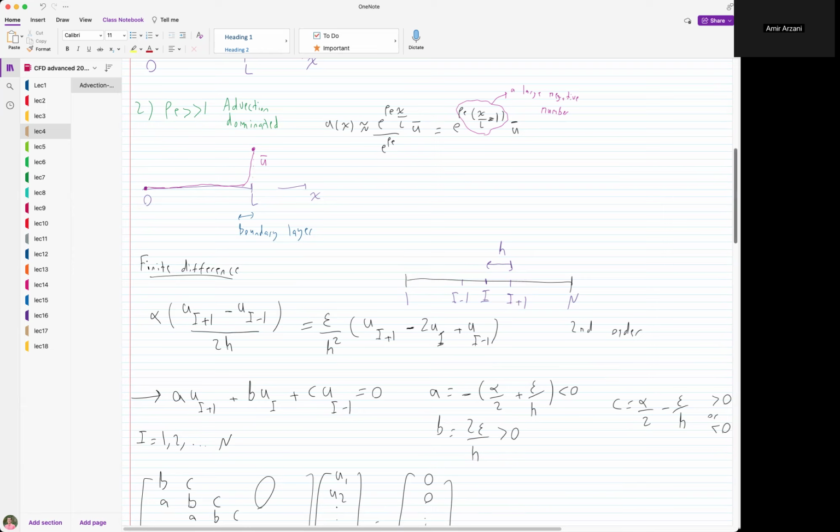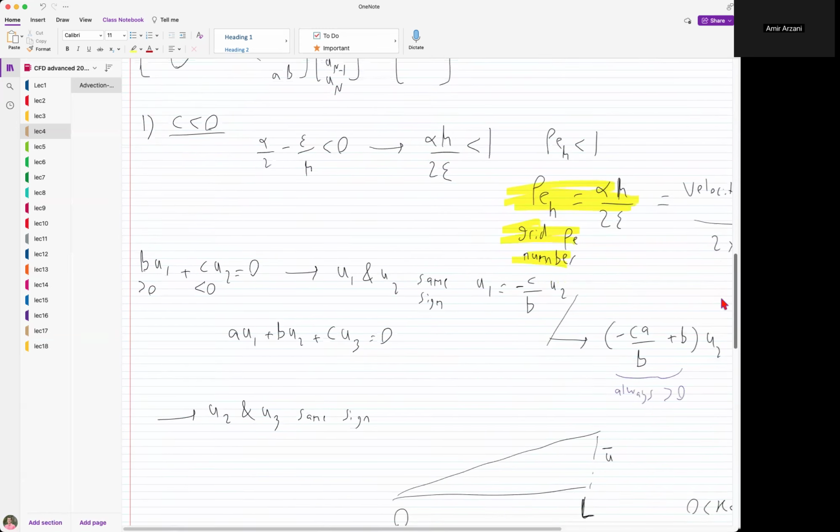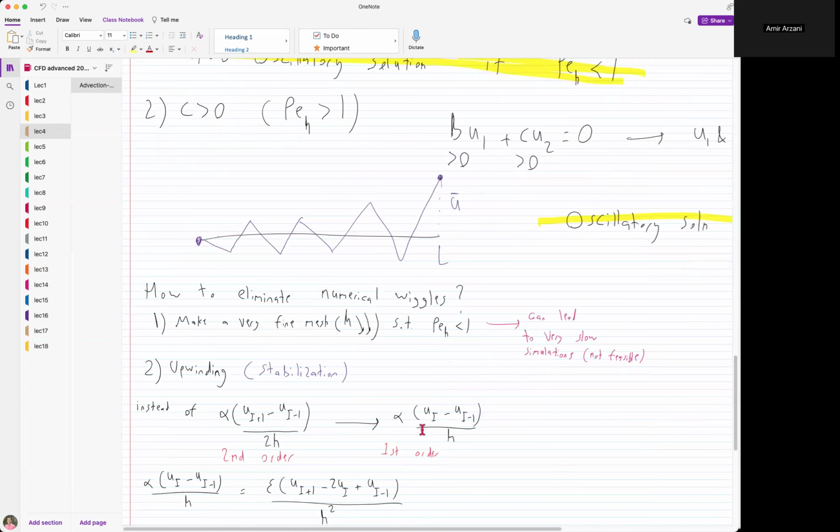So when I'm doing my spatial discretization around i, and I want to do a one-sided discretization, an upwinding, a first order discretization, I'm going to use the node that is to my left. I'm going to use i minus 1. I'm not going to use i plus 1 because I know the information comes from the left side. The flow is positive, alpha is positive, the velocity is positive from left to right. So in my discretization, going down here, I use u_{i-1} over h.